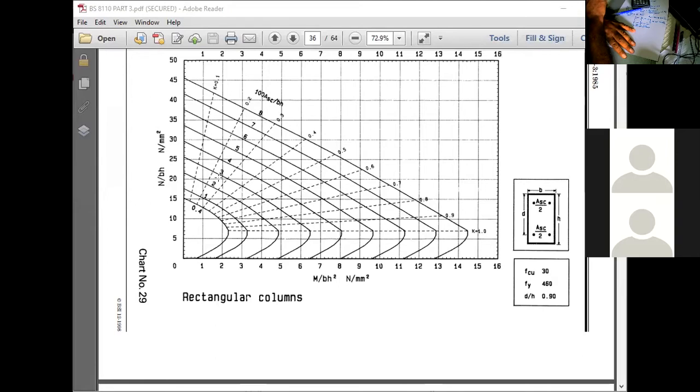But the general situation is that any tension in the shear wall is not desirable. Because of that, we have to make sure the shear walls are loaded to a reasonable extent. So if you have a very lightly loaded shear wall subjected to very high bending moment, you can design the wall, but designing the foundation will be a problem. I hope that has clarified the situation. Any other question like that?